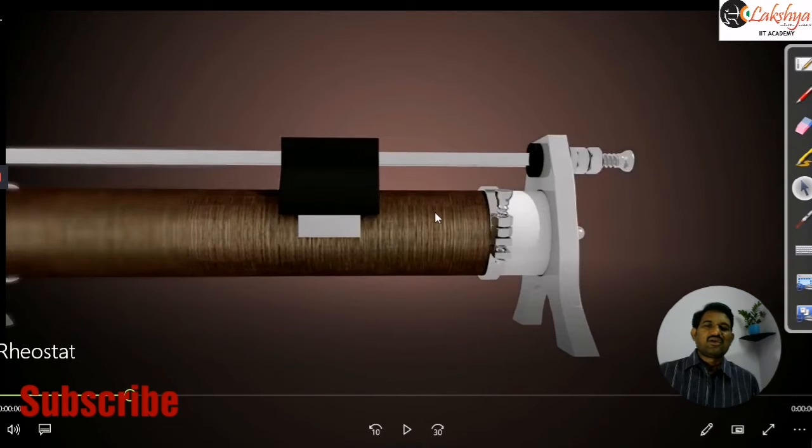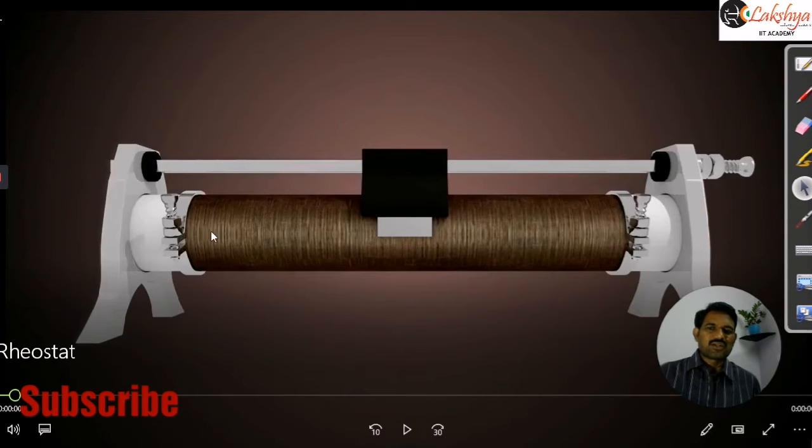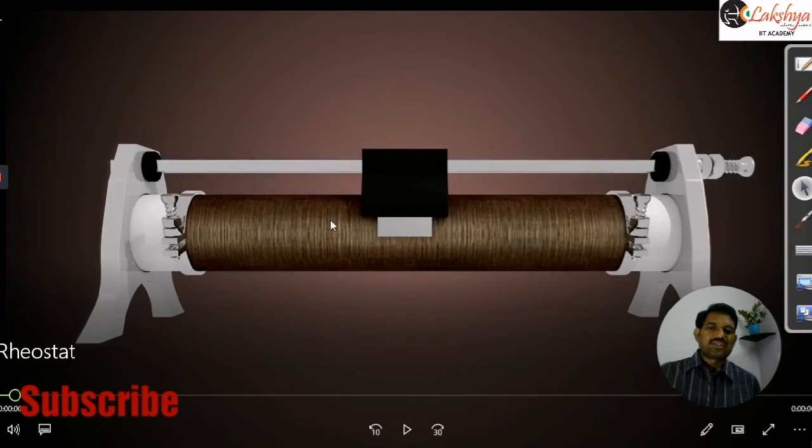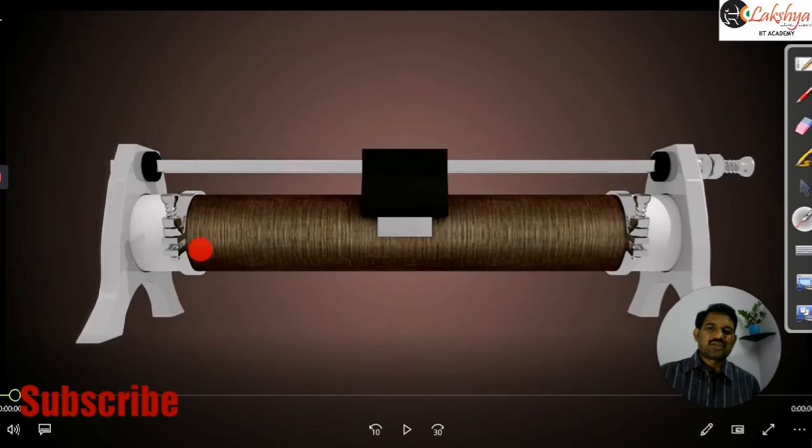Now suppose you are connecting like this. If the knob is here and you are making the connection between this terminal and this terminal, then current will flow only through this part of the circuit. It enters, for example, here, flows through this coil, and then comes out of the circuit like this. Or if you are connecting between these two terminals, with current entering here and leaving here, then it will flow only through this part. By moving this, we can put either maximum resistance or minimum resistance, depending on our requirement. That is the working of this rheostat.